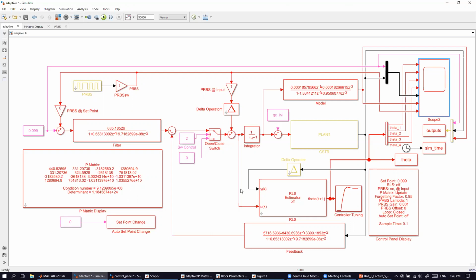All right. But it is important, right? Without injecting the PRBS, we wouldn't be able to identify any parameters. How big the PRBS needs to be? Okay, now this is extremely important and an extremely good question. No, there is no rule of thumb how big the PRBS should be, right? But the point is,